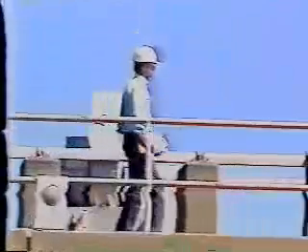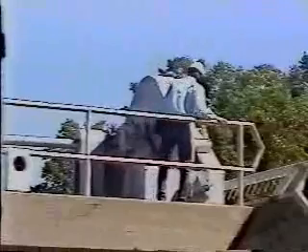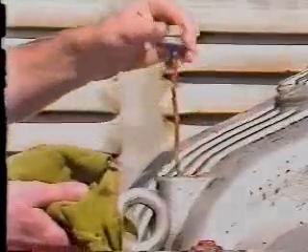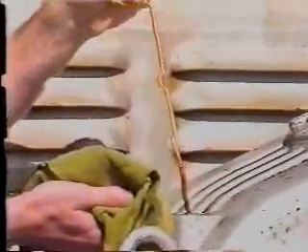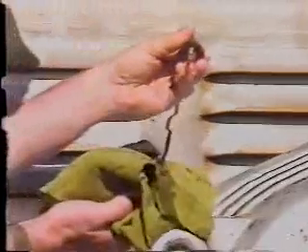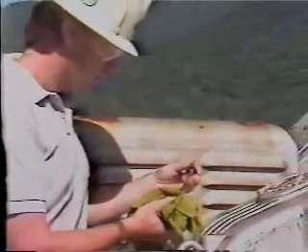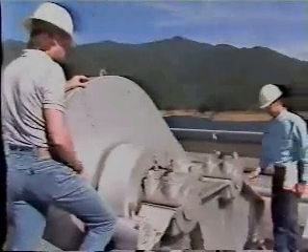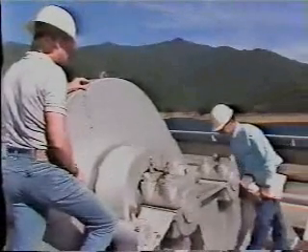Also look for surface damage and missing, broken, or loose parts. Damage may be caused by vandalism, normal wear, or failure of parts. Check that the reducing gears are properly lubricated. Next, look for other damage, such as corrosion.